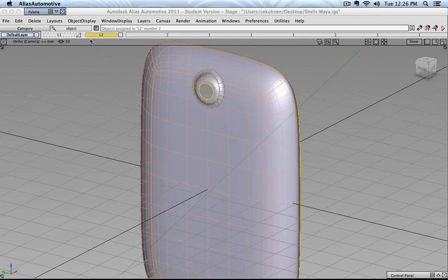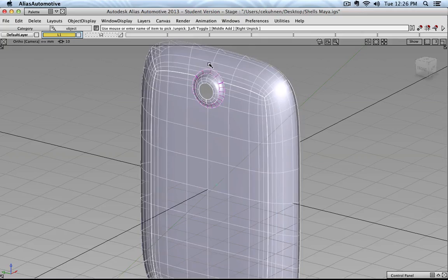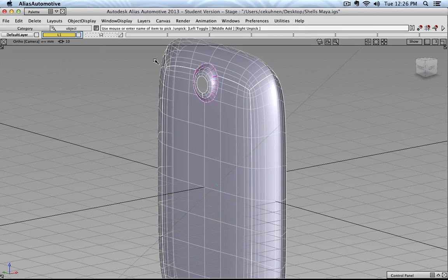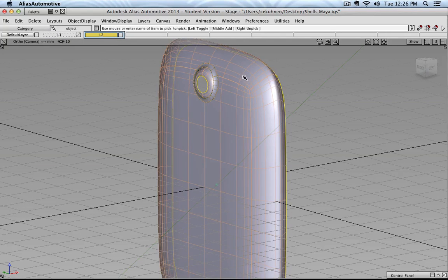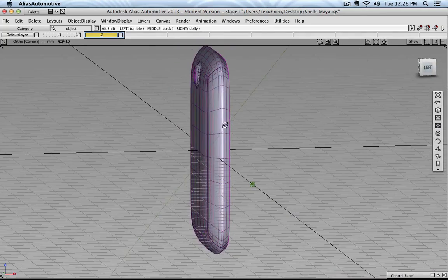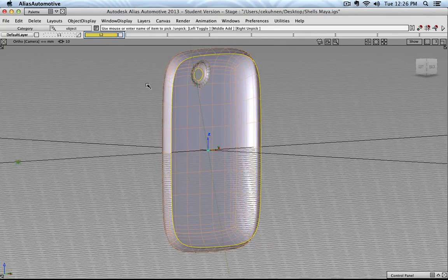Yeah, I just create another layer as well, so you can clearly see the difference, what happens. So what I have here is my original Alias mesh or the surface, and here on this layer I have my stitched surfaces. So the stitch command actually creates a duplicate object. So you're not messing with your original input surfaces, you just end up with a new duplicate part, which then we can select and safely mess with it without destroying our initial design.